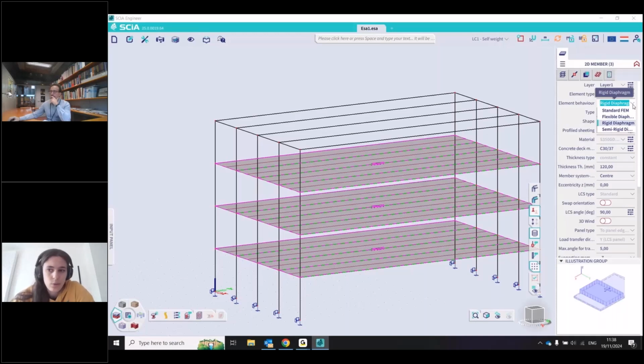It will have stiffness for bending, for shear, for everything. But it will lead to some non-equal distribution of the loads. You will have some extra loads arrive in the middle, and on the sides, the deck will actually load off some of its loads to the columns, for example, rather than to the beams first. And this will bring you to some quite different results than you generally anticipate.